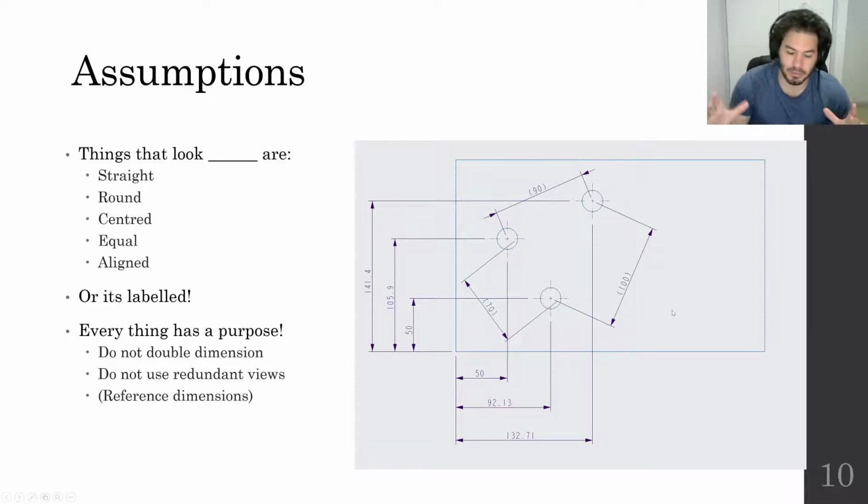All right. Let's assume I've got some random plate and it needs to go on to some other part that already exists that's got these 3 pins that come out of it. So I just need these 3 holes. The problem is I go on and measure these pins up and they're these weird distances apart. It's at some weird angle. It's really hard when you're in a workshop to work with angles. Angles are horrible things to work with. Protractors are horribly inaccurate pieces of equipment. So we never work with angles if we can ever avoid it. By far the best thing to give a tradesperson is a series of Cartesian or linear dimensions. So exactly this many millimeters from a nice corner that they can put a ruler on and they can mark. So that's the easiest way for them to get the locations of these 3 holes.